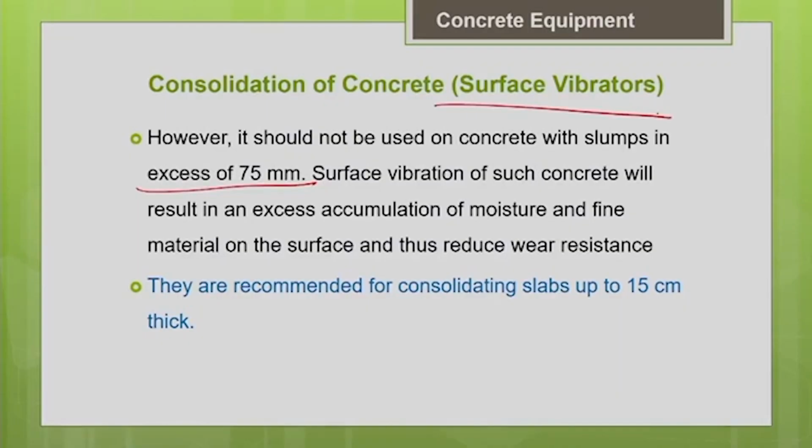Water and a thin layer of paste will come to the surface of the concrete. So, when we use surface vibrators, that will make your surface layer weak. Particularly for floor slabs, where surface strength and wear resistance are very important, we should be very careful regarding this kind of segregation. It should not happen.